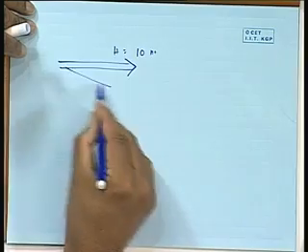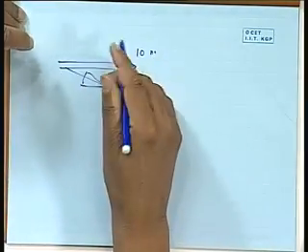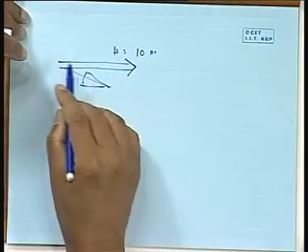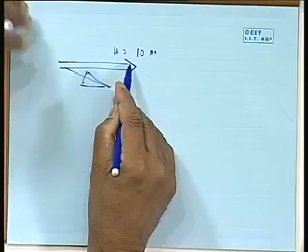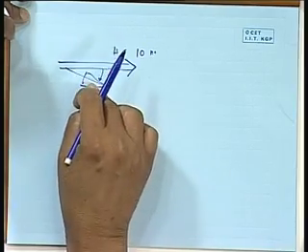We will give an example of just one wave, just for illustration. Supposing in a 2D case you assume that only one wave was coming, of some height. Let us say some wave was coming of height 10 meter in this direction, and my ship was moving in this direction. So I would find out, as if there was only one wave coming this side, 10 meter height. It will have certain energy. So I would find out what is the ship response to this wave.